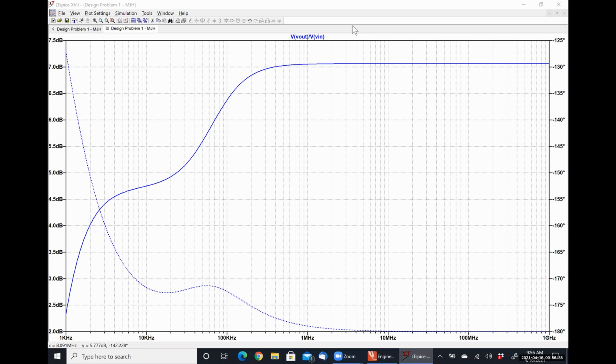So all of the small signal analysis that we've done to this point is technically only valid in what we're going to call the mid band, okay? Below the mid band, the capacitive effects of our bypass and coupling capacitors dominate, which is why we have this weird frequency response over here on the left-hand side.